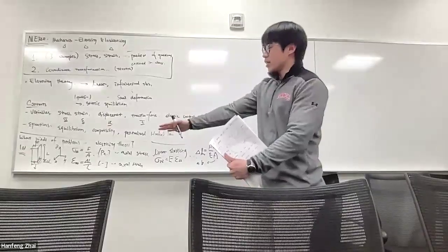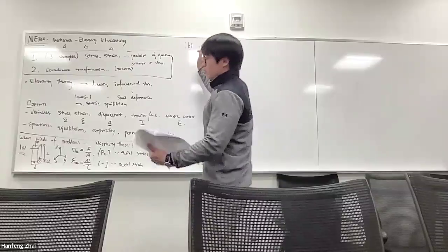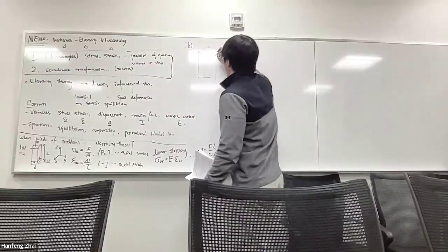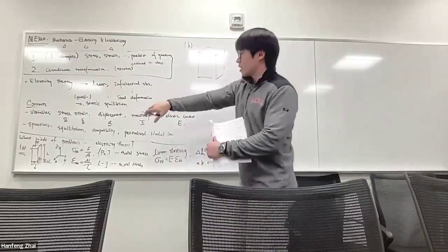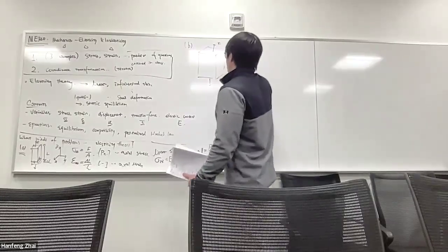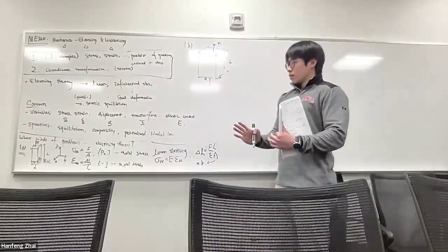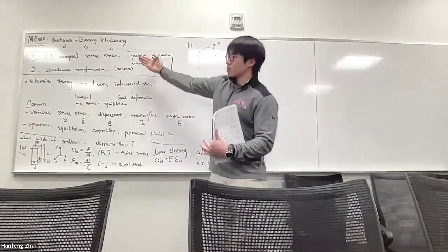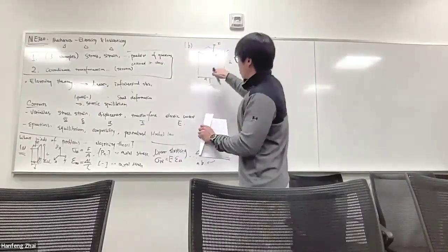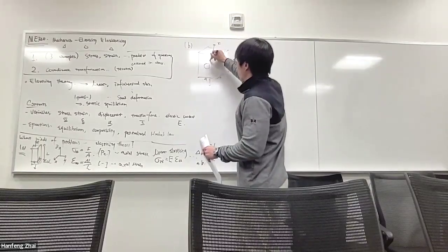And on top of A, can we introduce a more interesting problem or example? We can keep the same rectangular cross-sectional elastic bar, apply the same tensile loading, also with length L, A and B. The only difference, which takes us into the graduate level part of this class, is that we introduce a geometric difference in the material, where you have a cylindrical hole.